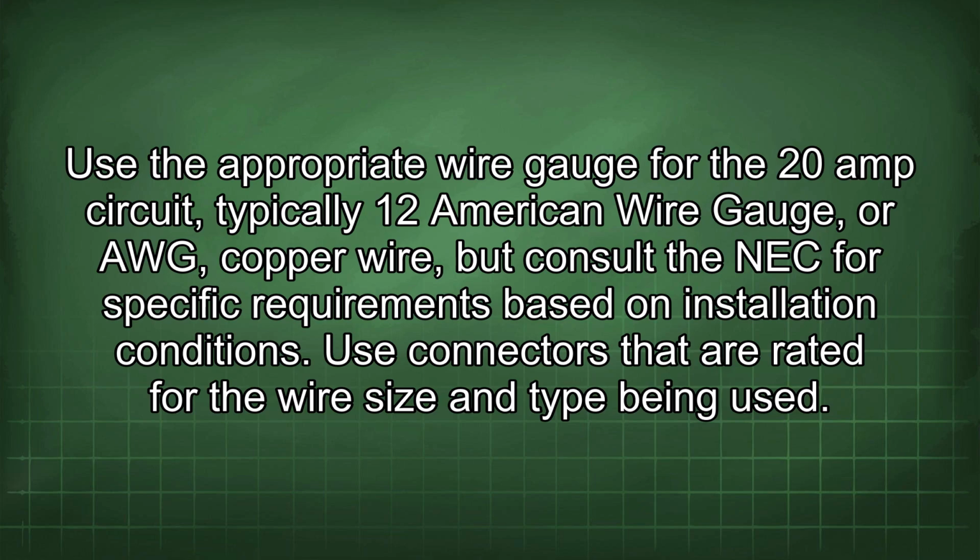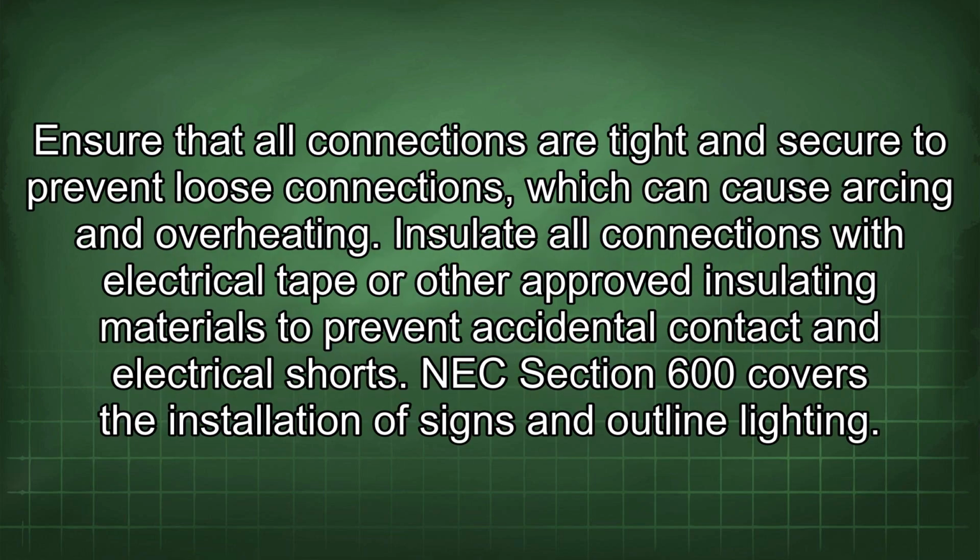Use connectors that are rated for the wire size and type being used. Ensure that all connections are tight and secure to prevent loose connections, which can cause arcing and overheating. Insulate all connections with electrical tape or other approved insulating materials to prevent accidental contact and electrical shorts.